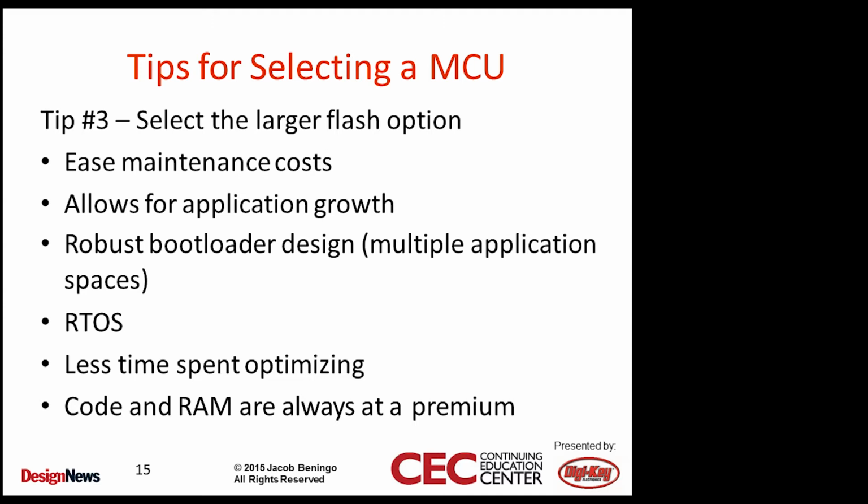Then that way you don't say, hey, I'm going to get a 32-bit part or a 16-bit part, kilobits for flash space, and discover that, oops, I actually needed 64, but now I have to go back and rework a whole bunch of boards that are in the development environment because I chose the wrong part and things like that. Start with a larger flash option and then work your way back.